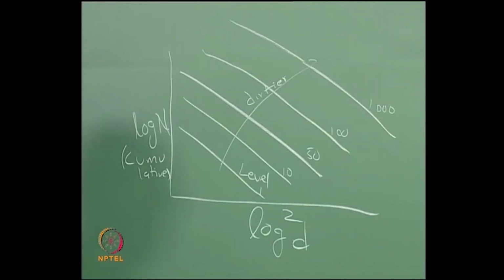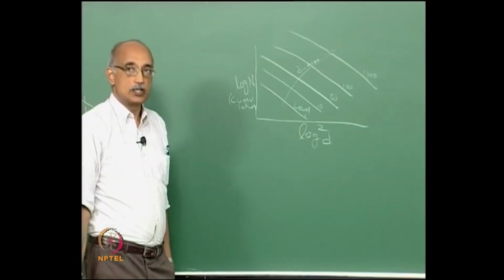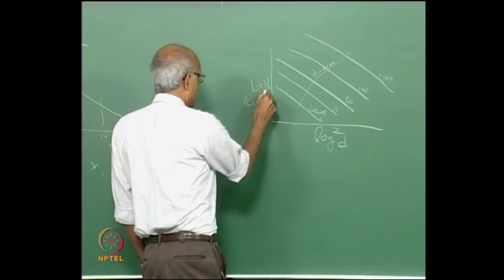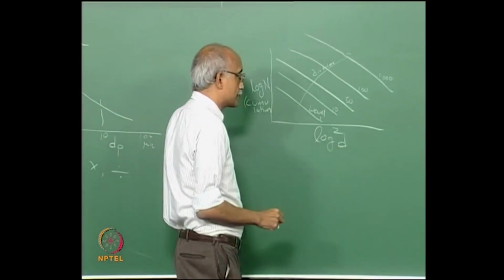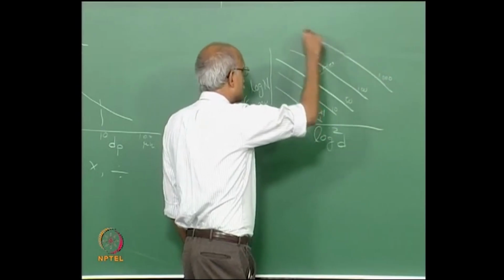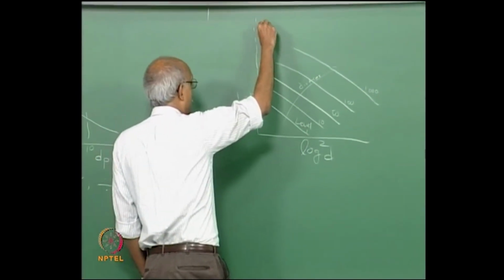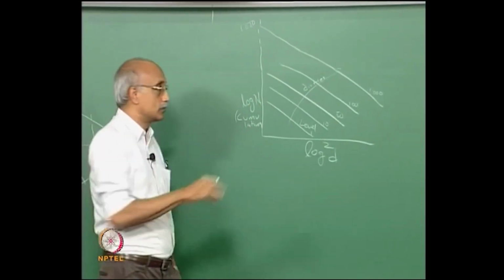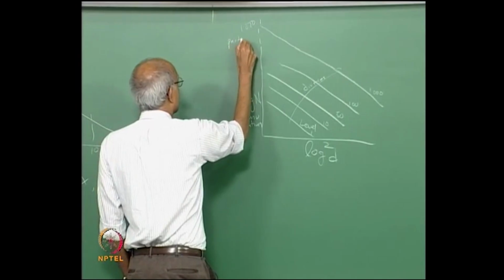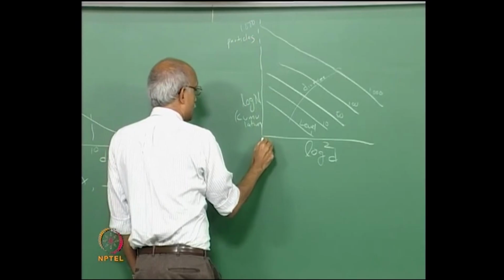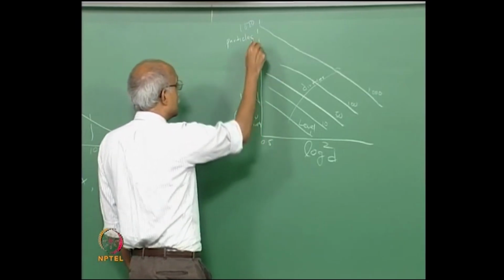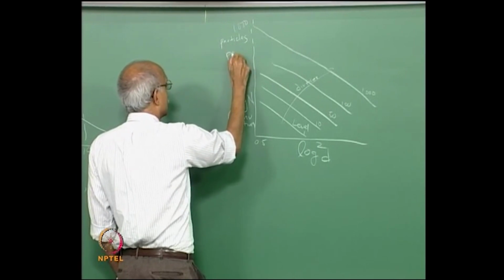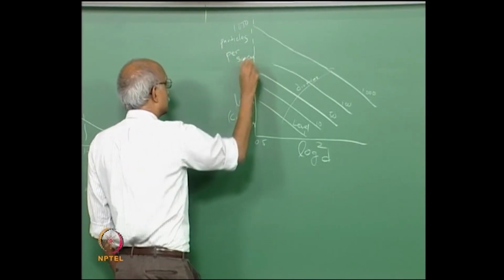So, for example, if I say that this table is a level 1000 surface, what it means is that if I plot the particle counts versus the size, it will lie along this line where the intercept on the y axis will correspond to 1000 particles, and this line starts for this purpose at 0.5 microns, 1000 particles per square centimeter.